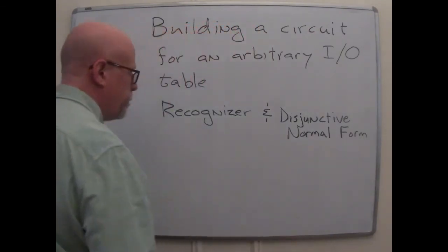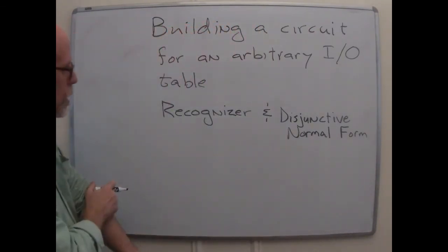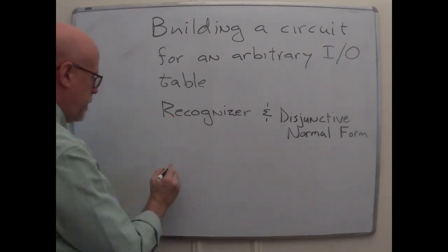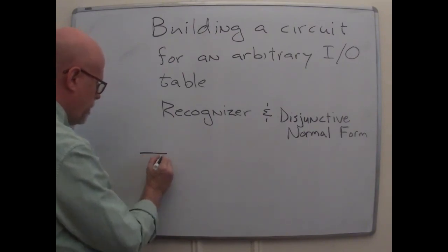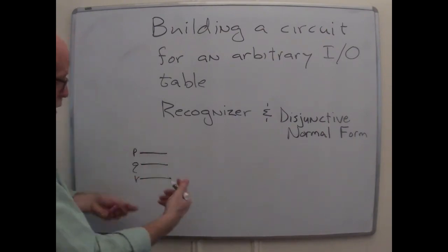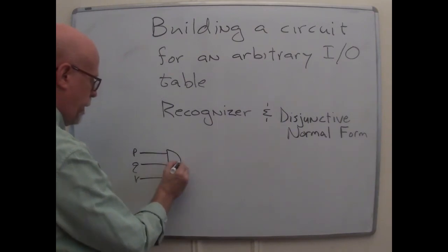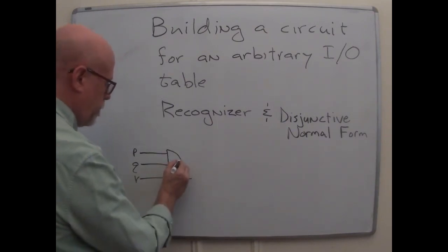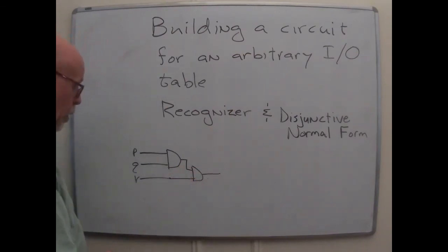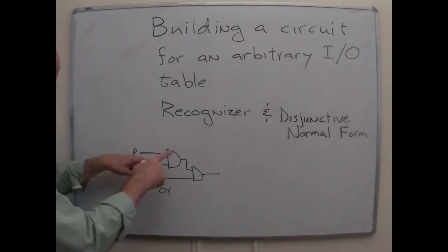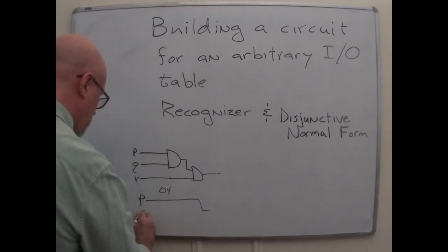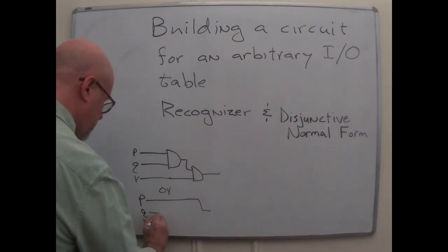Let's first talk about a recognizer. I like to build in a shorthand at this point for when we're doing recognizers. It's that you can take a circuit that involves three inputs, like P, Q, and R, and you want to AND them all together. That would mean you should have to build an AND gate for that one, and then take this guy plus this one's output and feed them into another AND gate, and that would be your output. Or, because the associative law is true, you could do P would be the last one, and it would be ANDed with Q and R.